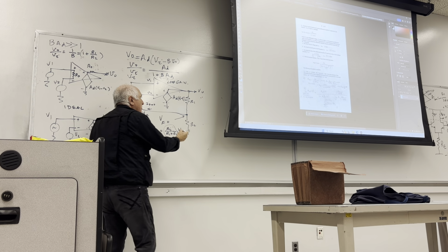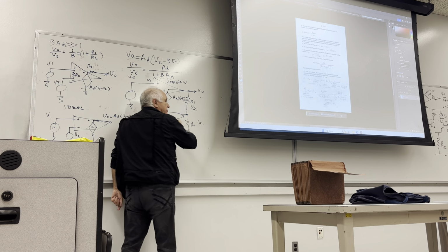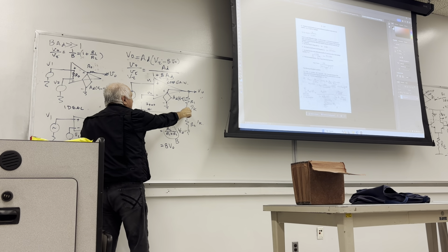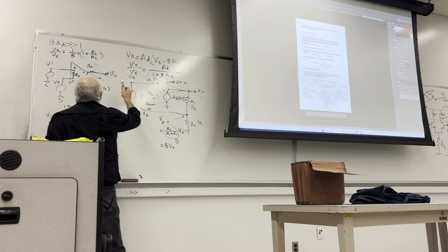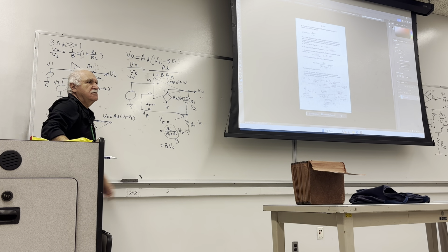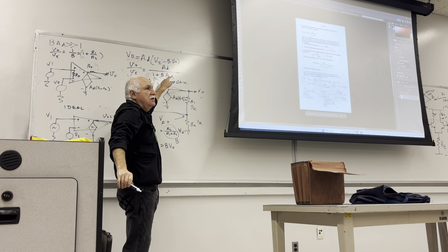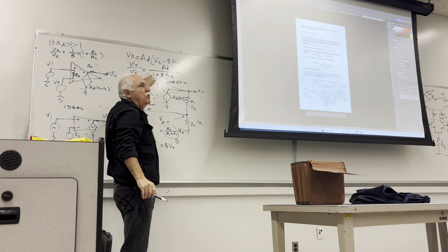For example, 9K, 1K. It makes this 9 plus 1, you got 10. You got a gain of 10, exactly a gain of 10. Provided this is much greater than 1.